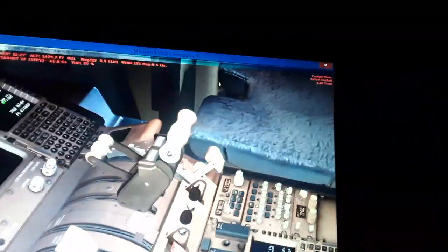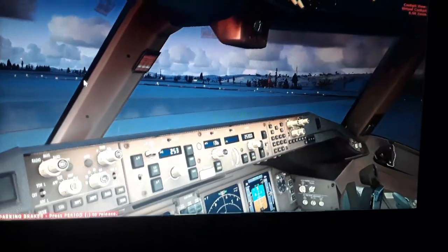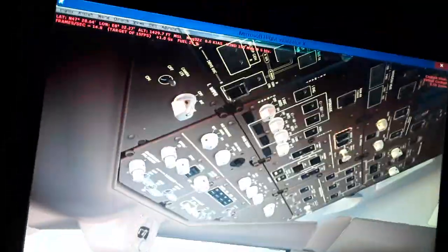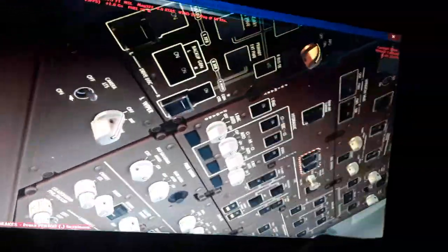So we have the horizontal trim stabilizer. I'm gonna talk to you now. The horizontal trim position like this, up and down, and you have the horizontal trim. You can use the normal and the alternate tab for the pitch trim also. And also we have the auto trim system from the autopilot here, and the auto throttle. So we have a malfunction of the C1 and C2 hydraulic systems over here. Hydraulic pumps pressure is low, so there's no auto trim.